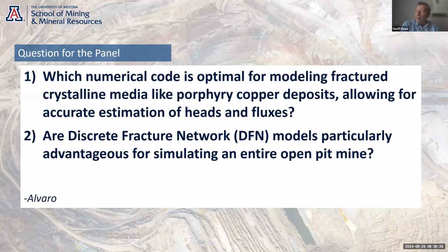We can take values of porosity and storage, and we can take values of friction angle and cohesion and so on, and we can run statistics and we can do sensitivity analysis on models. But the overriding control is the geology, and geology does not lend itself to statistical analysis.